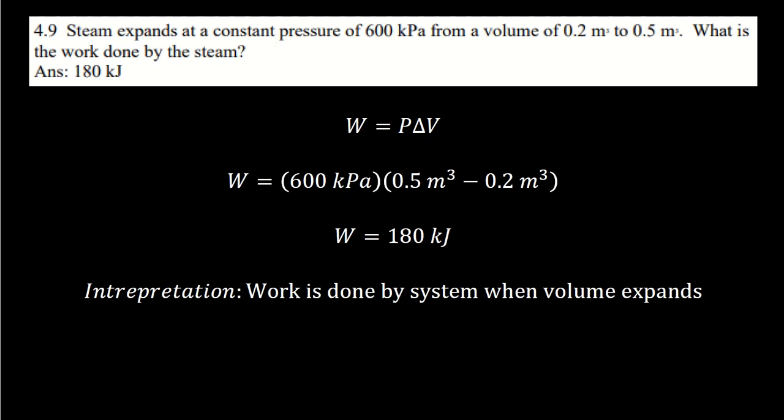4.9 and 4.10, these are just similar examples about steam, but looking at it from positive or negative work. Let's look at steam expanding at constant pressure at 600 kilopascals from a volume of 0.2 to 0.5 cubic meters. What is the work done by the steam?